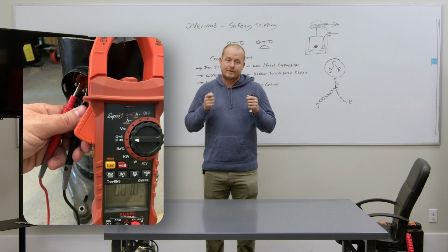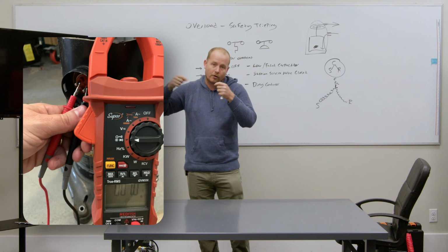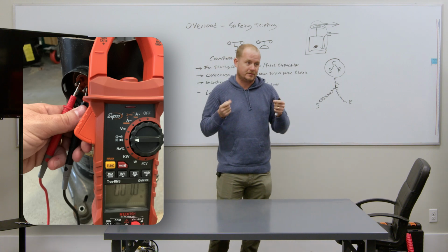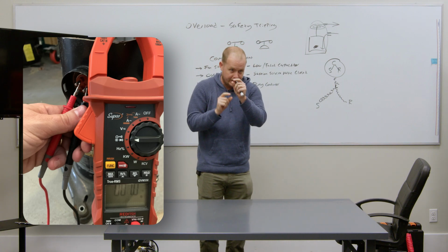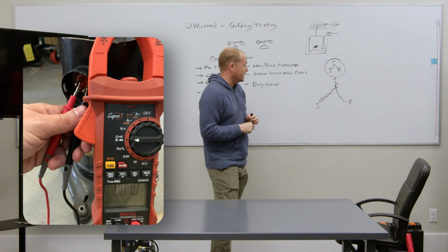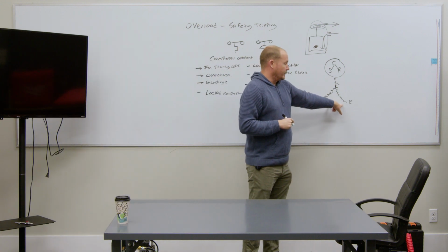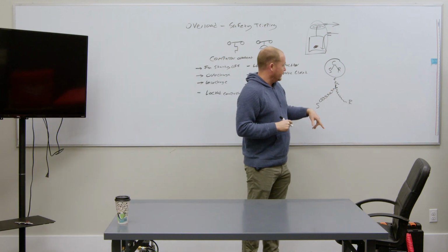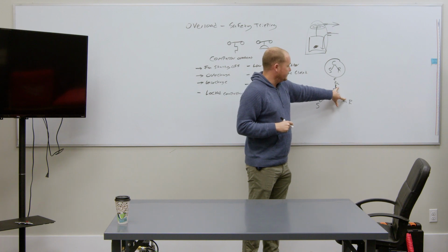Because I don't want any sort of, well, the wire wasn't on all the way or whatever to get in the way of this procedure. So then you take your leads and you measure across. So you're going to read ohms here. Then leave your ohm meter in between two of these.